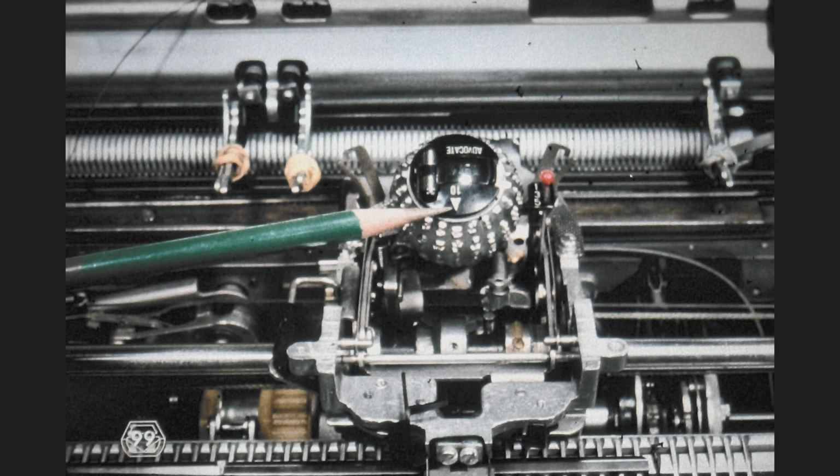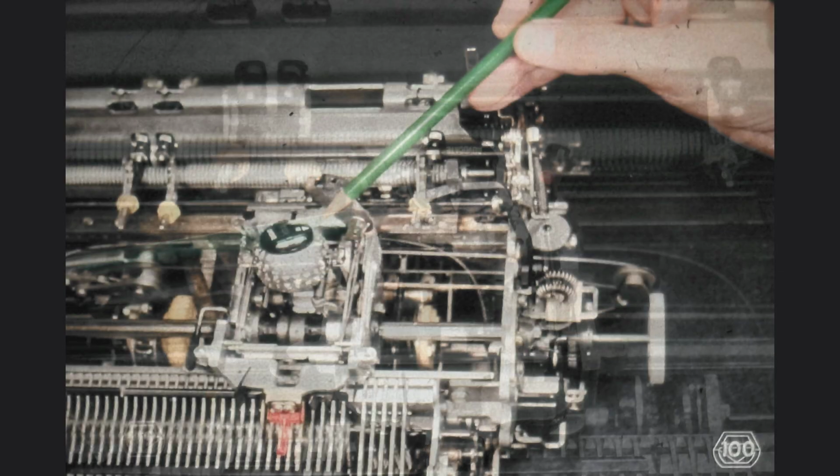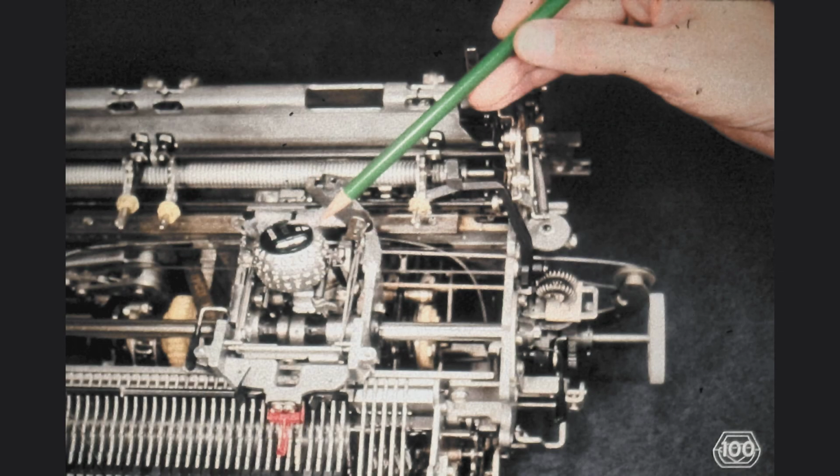At this point, let us release the rotate spring tension. First, we hold the element with our left hand and continue to turn the hand cycle wheel so that the rotate detent comes out of engagement with the element. Then, we slowly allow the element to rotate clockwise and count the number of turns it takes until the element comes to rest. The spring took slightly more than 3½ turns before it exhausted its tension.